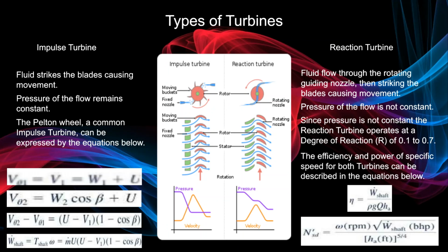Power specific speed can describe whether axial or radial will be more efficient. Efficiency can be simplified to the equation: absolute value of actual work over reversible work. However, if the actual and reversible works are unknown or unobtainable, the equation below can be used to calculate efficiency. But typically, calculating actual and reversible work will be much easier.